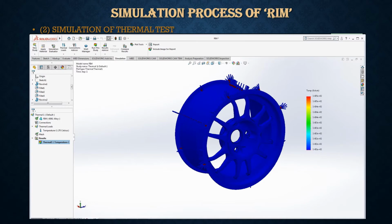Next we will proceed to the simulation of the thermal test. The steps are a bit similar, which is we start with simulation, new study, click thermal. The difference is just we click thermal, then select material, which is the same, alloy 6061, which is aluminium.